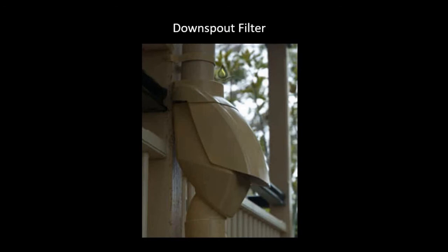So if there are pine needles or some particulates like that, the screen will catch them and it will rinse it to the bottom of the screen, supposedly. And then periodically you come around. These are positioned at easily accessible heights. So if you had a two-story building with a downspout, you'd want to have it down at ground level where you can reach it about eye level. And then you just flip that open and take your hand and clean out the screen and go to the next one.